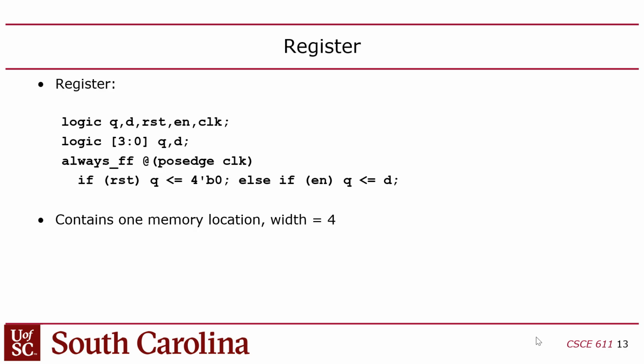Okay? All right, so last week I got into microarchitecture and how to design the RISC processor, and I assigned lab 3. But we were pretty light last week, so I'll review what I talked about. I went over sequential logic, clocked logic, and in particular this register. And so in your CPU design, you'll need registers to hold values that are used in subsequent clock cycles.